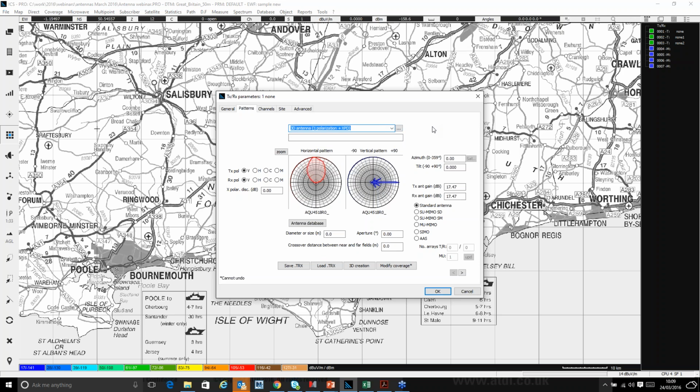So I have a PLT, in this case a 3D PLT, and the difference between the files, typically the 2D PLTs will be slightly smaller in terms of size, and if you open them up as well and look at them with some sort of text editor, you'll see that the 3D ones, as they're referred to, are an array of values, whereas it's just a couple of columns for the 2D. So if you're not sure, have a look at the file.